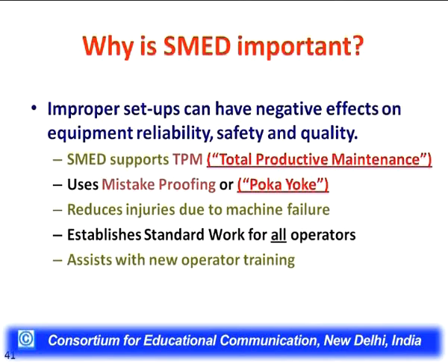SMED streamlines the changeover process, streamlines the setup process. If this is not implemented, mistakes are possible. If the wrong setup is done and the machine is run, it may damage the machine. It may damage the spares of the machine also, and the machine will become unreliable and a source of trouble for the technical people. So, SMED supports TPM also.